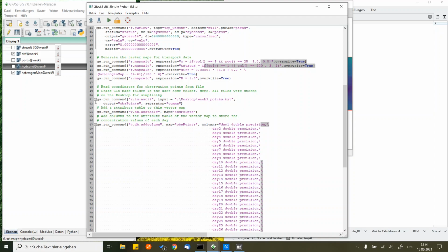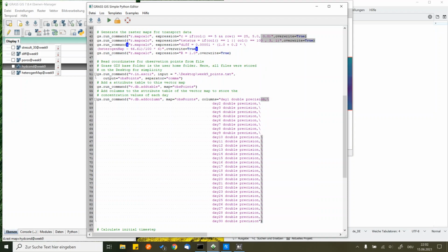We have to define boundary conditions, so we will have no flow boundary conditions on all sides, but the transient boundary conditions on the left and the right, so that the tracer can escape our domain in flow direction. As I already said, I'm introducing the diffusivity similarly to hydraulic conductivity and porosity based on the heterogeneity of the domain. And I'm neglecting any kind of transmissivity at this point. At the same time, I want to take daily measurements at some observation points.